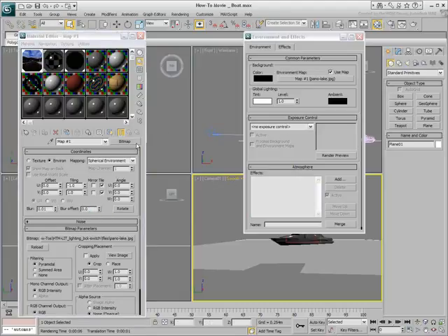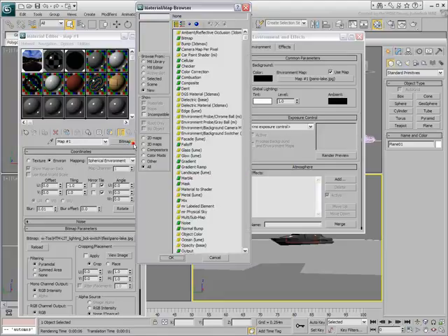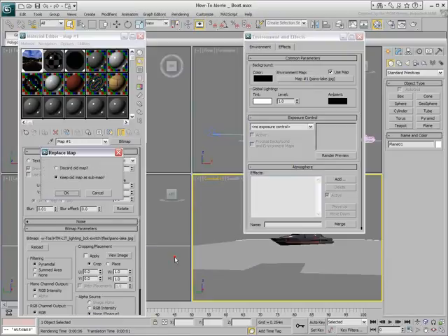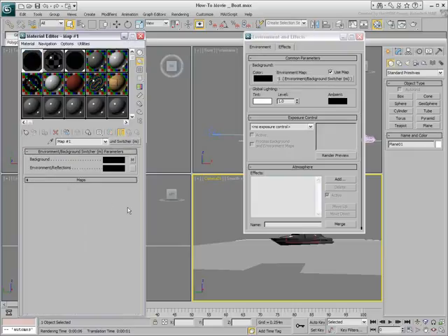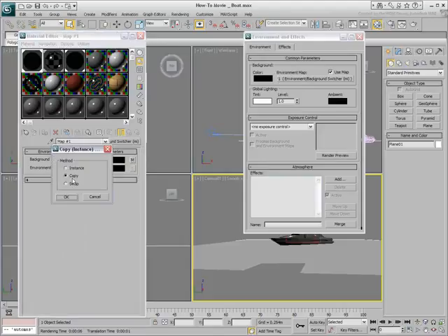At this time, the environment map consists of a bitmap you instance into the material editor. Change the bitmap type to an environment background switcher shader. Notice how this is a mental ray shader and will not work with the scanline renderer. Make sure you keep the old map as a submap, since you still want the panorama to display as a background. Make a copy of the background into the environment reflections channel.